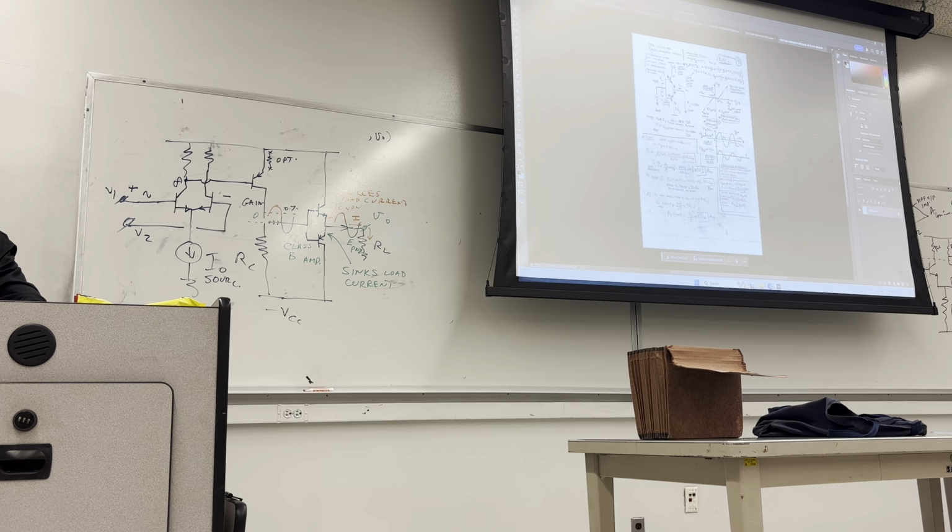while the input voltage hasn't exceeded 0.7 of a volt. Similarly, for the negative one in here, you need again 0.7 from here to here to have an emitter current. So that means until the input voltage goes to negative 0.7, there is no output. Here, two flat zeros momentarily when a sinusoidal drives the input stage.